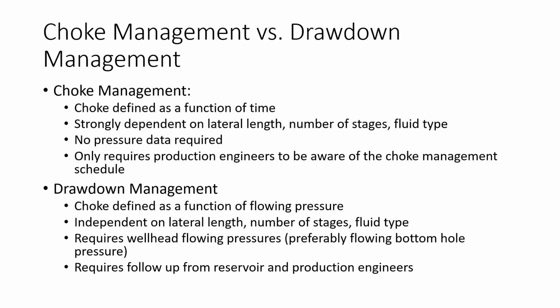For drawdown management, choke is defined as a function of flowing pressure. It's independent of lateral length, number of stages, and fluid type. It requires wellhead flowing pressures, preferably flowing bottom hole pressure, and it requires follow-up from reservoir and production engineers.